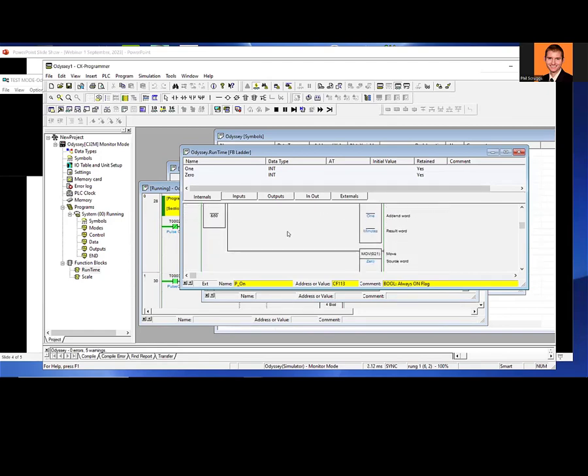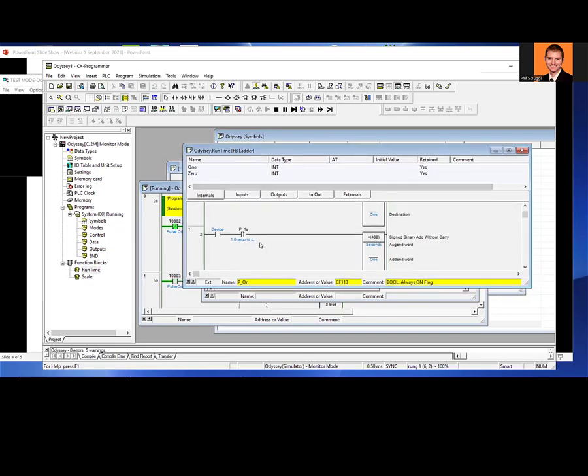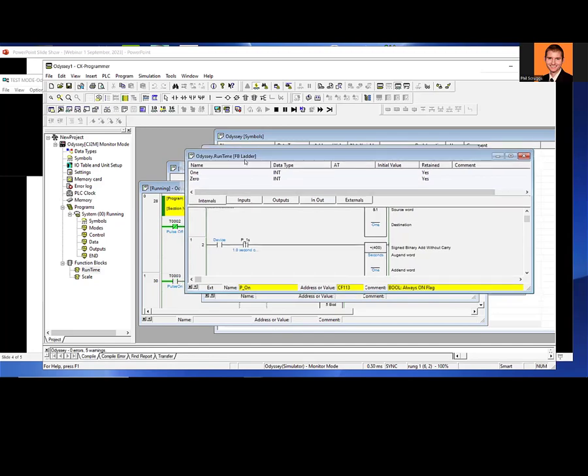minutes. Then minutes cascades into hours, right? So seconds cascading into minutes, cascading into hours. Typical function block for that. Again, lots of places you can find that kind of stuff online, and I usually throw those into my classes. People like that because runtime on everything for data collection is very useful. So pretty standard way of doing things, but that's a look at the function block. And I do have a little scaling block here, and they have libraries and lots of other stuff also as needed. So that's a look at the CXOne software.